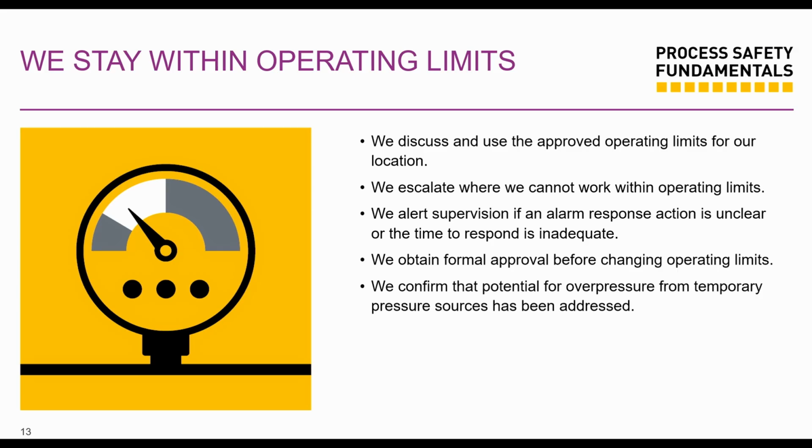A scenario also could be, you're increasing throughput, you're pushing a lot because you want to meet aggressive production targets, and then your pressure and temperature spike above what the system is designed for. Your operating pressure, your design pressure, you're almost exceeding those, and then you start having thermal stress, and then a flange fails. You have a flammable release because you are operating outside your safe operating limits, or a heater is run above design temperature to boost throughput.